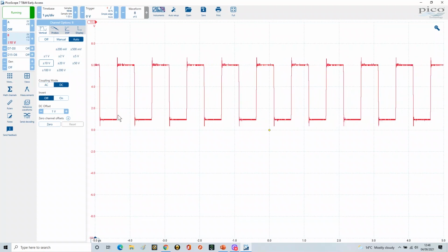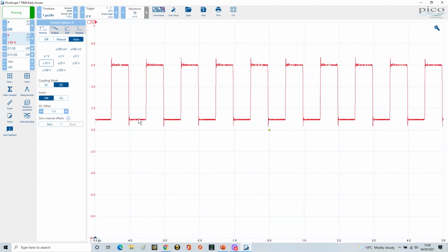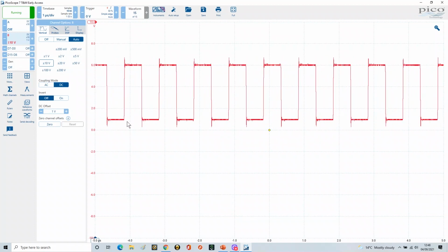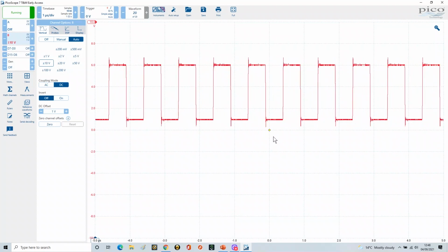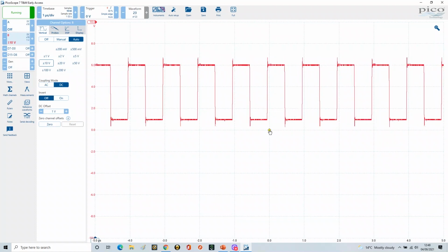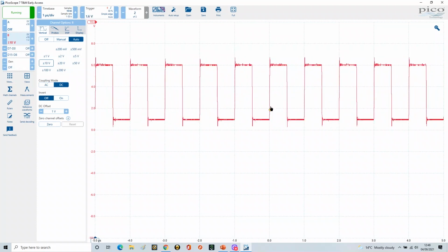Exactly when you would do this within an analytical environment, it's really hard to know, but there are times when it's actually relevant. What you will notice now is the waveform isn't locked because we're outside our trigger. Our trigger was at 0, but of course the waveform is now out of range. So if I take my trigger point and move this up here, we can now lock it so that the trigger point is in the midpoint of our waveform-ish, and therefore it locks the signal. So we can see the pre-signal and the post-signal against that trigger point. So that's the DC offset.